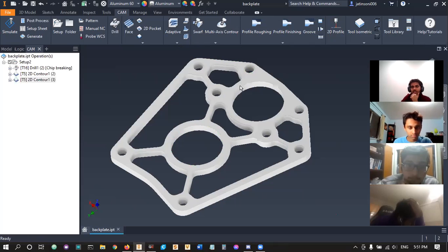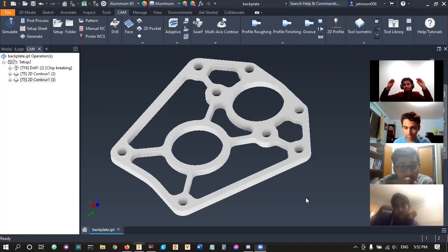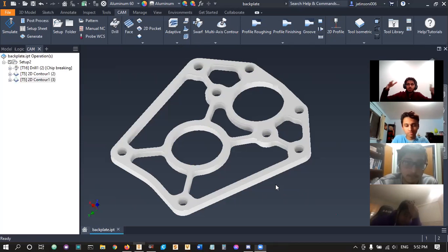How do we hold the aluminum sheet to the CNC? Right, so that's where we use clamps. So the edges of the CNC have clamps on them, and you just clamp the edges of the aluminum and you cut in the middle. But that's okay for the whole big sheet because we have 4 foot of space to work with. But if it's for this small part, if you put clamps on this, you don't have any place to do the pocketing.